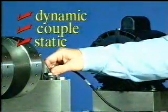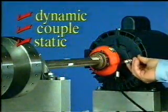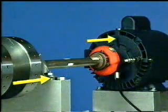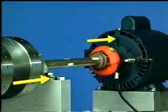For dynamic unbalance, couple unbalance, and static unbalance, the axial readings across the coupling should be in phase. Again, in phase is normally considered to be within 30 degrees. Another consideration in phase measurements, especially in the axial direction, is the direction of the sensor.